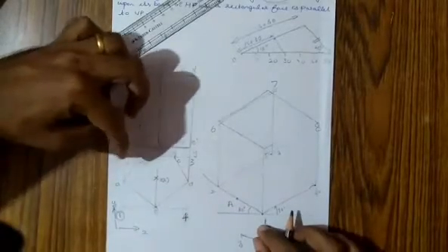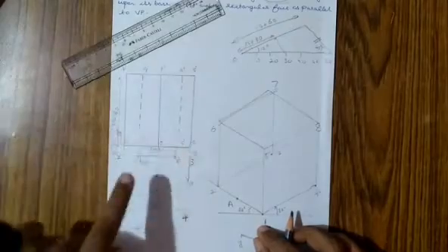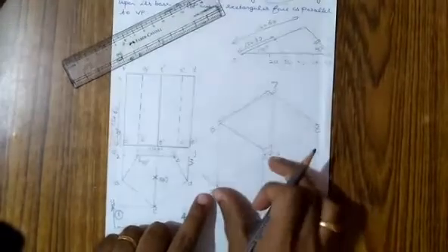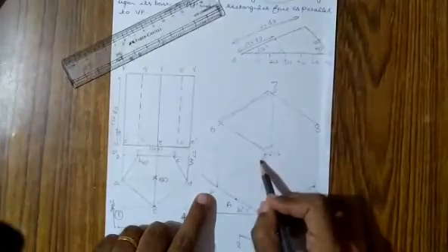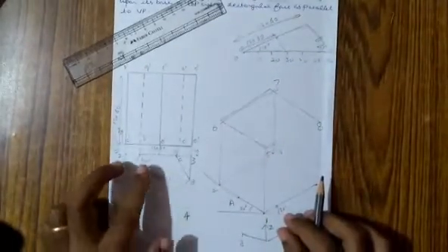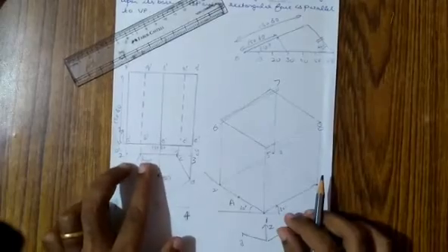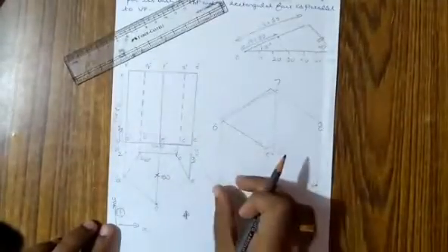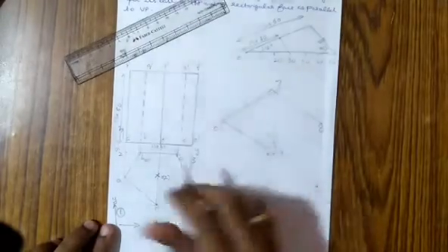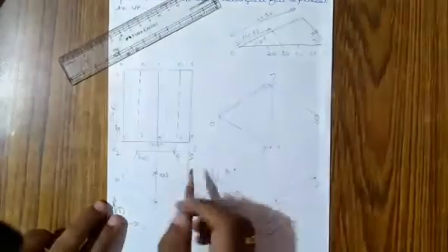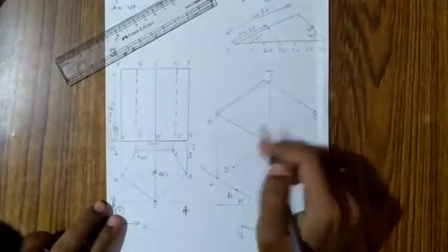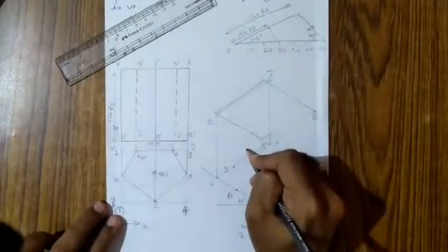Next, on 2, 3 you are having 2 points B and C. So this is your 2, 3 and on that you will be having B as well as C. Now how to locate it on the isometric view is you take the distance from 2 to B, the small distance, and you mark it over here. So this is going to be a point B. Next you take this small distance from 3 to C here, from 3 backwards. This is going to be a point C.